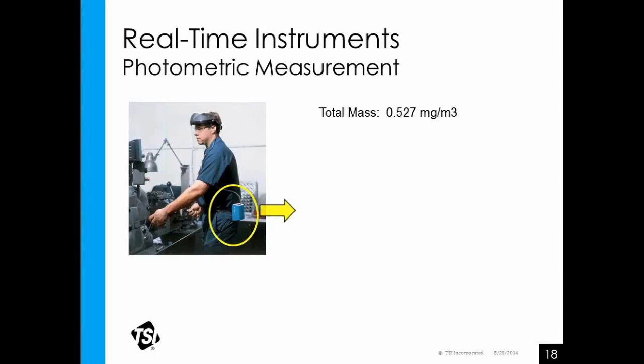Now, our average is low, our average is safe, but is this a chemical or contaminant or some kind of process, some kind of exposure? We don't want people above the level of 1, or we don't want them above the level of 2. We may want to focus some resources on what that person is doing at those times, and maybe that's where the engineering controls are put in place, or that's when the respirator is needed.